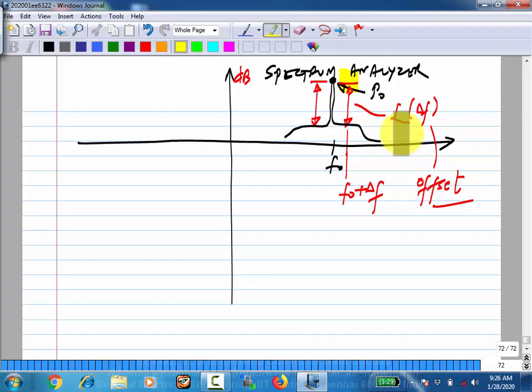Is this okay? So you can measure it. There are also specific phase noise analyzers that will detect the phase of the signal. I mean, they will have some ideal clock. Ideal meaning much cleaner than what you are expected to measure. Most measurement instruments work like this, right? You want to measure something, and inside the instrument there will be a standard that is much better than what you are trying to measure in different ways, much more accurate. You compare the two and make a measurement.